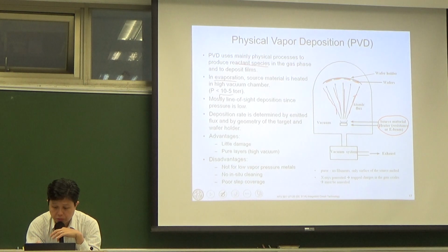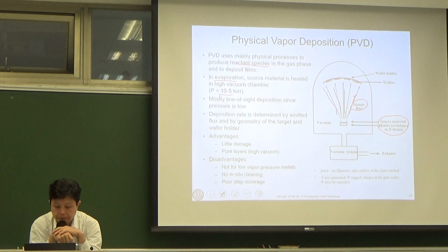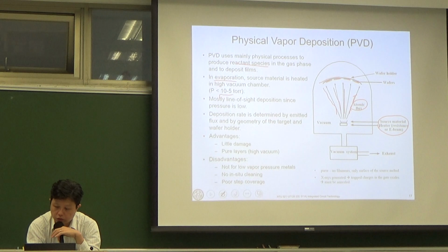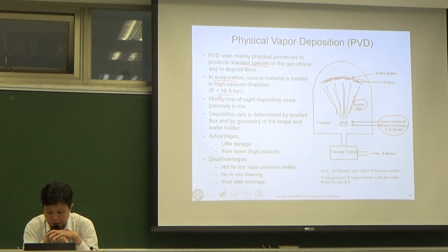And the deposition rate is determined by this flux. Okay, we have this flux, and it's also geometry dependent. The wafer topographic profile will change this deposition rate, and also this wafer holder, how you place it.